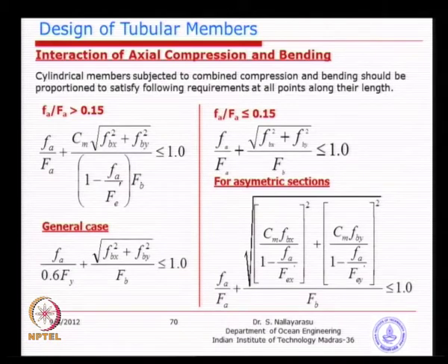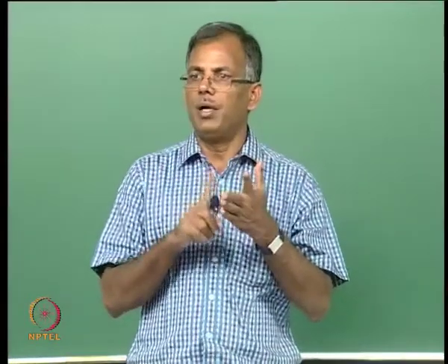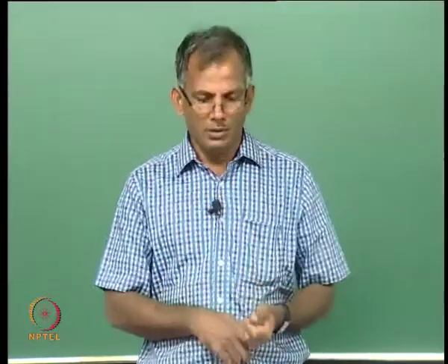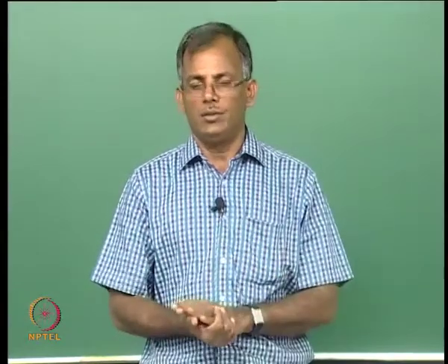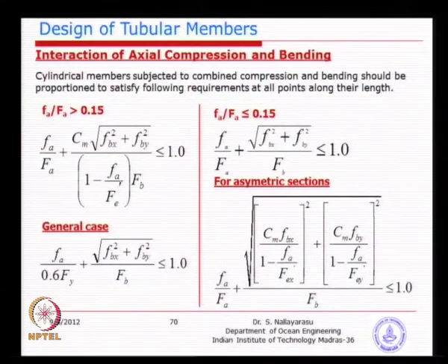Now, finally, we have done the allowable axial stress, allowable bending stress, allowable shear stress and then allowable hoop stress. Now, what we need to look at is how do we combine all of them together. The straightforward approach is to first look at the general case. We have an applied stress and an allowable stress. We will be happy and we can conclude if the allowable stress is always greater than the applied stress, a linear superposition.